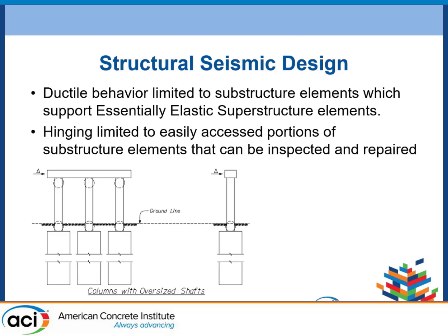So the principles behind this are that we have, as a state, chosen to limit ductile behavior to the substructure element and facilitate an essentially elastic superstructure. Now, Dr. Huff just talked about other strategies whereby maybe that's not always necessary, but in South Carolina, the design code and the design assumptions are based on that fundamental assumption.